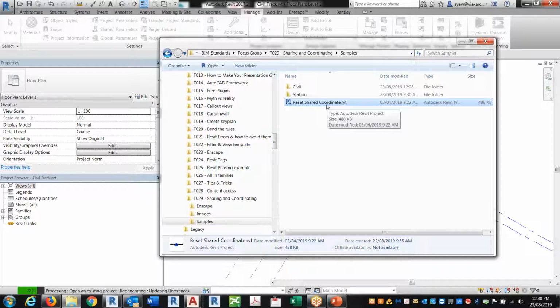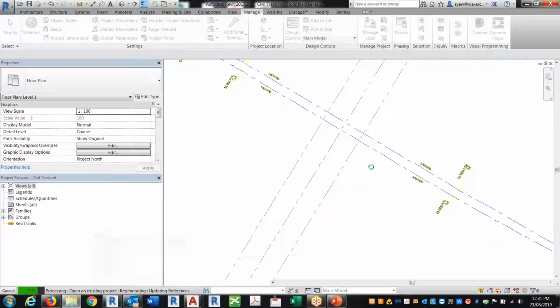If you don't understand it, that's fine. I try not to confuse people. I just want to show you the steps that I would take to do it, right? So the first step I did was to always establish your 0, 0, which is right there. The next thing you do is link your AutoCAD file into your Revit file, move your origin point to where you want the new origin point, and then you acquire coordinates. Once you acquire the coordinates, that becomes your new coordinates.